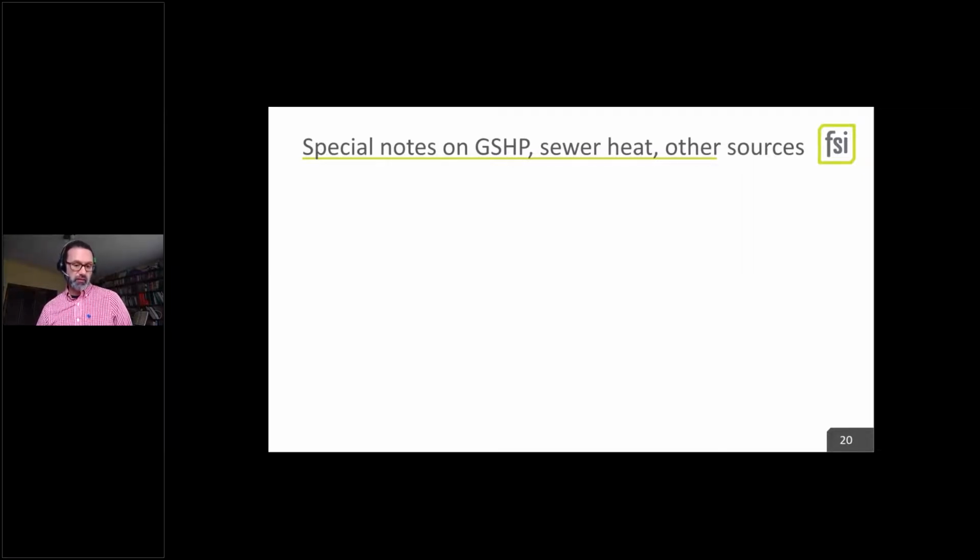But you know, there are sources of heat like that. So if you've got a privately owned lake, you can do a geo loop. You get, give or take, 4 cooling tons per acre of surface area. We got to help rescue a winery that was using a geo loop for its heat exchange, a lake loop.